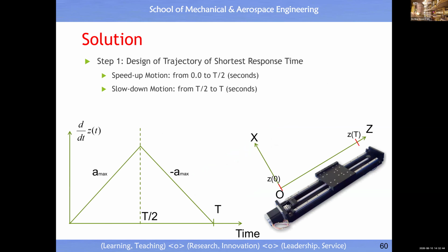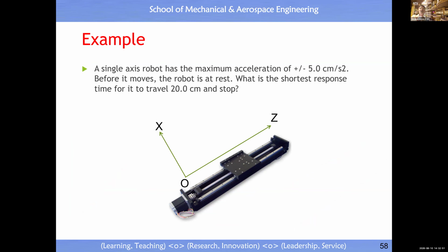One is maximum acceleration, another motion is a maximum deceleration. Pay attention for this application. The slider initial position is 0. The final position must stop at the 20 cm. You cannot say I just pass through. It's not this scenario, understand? It just must stop there at the location 20 cm. Velocity must be 0.